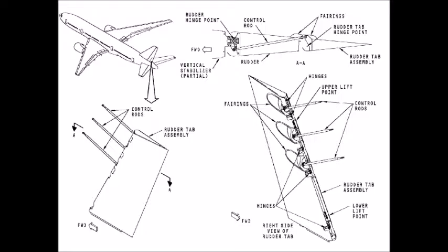The rudder PCUs have internal stops that limit the rudder surface deflection. The rudder has a maximum movement of 27 degrees in both directions at low airspeed under no load conditions. Under loads, the maximum PFC and ACE command signals move the rudder to a nominal position of 25 degrees in both directions at low airspeed.